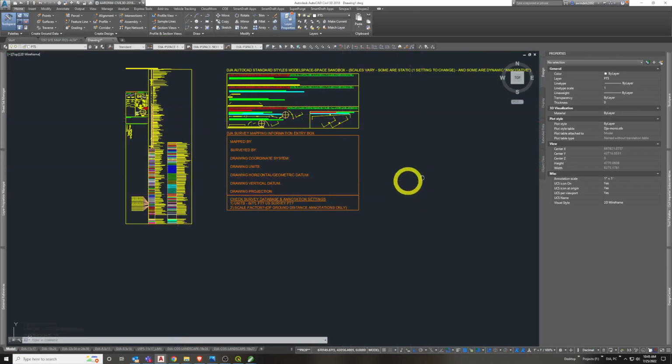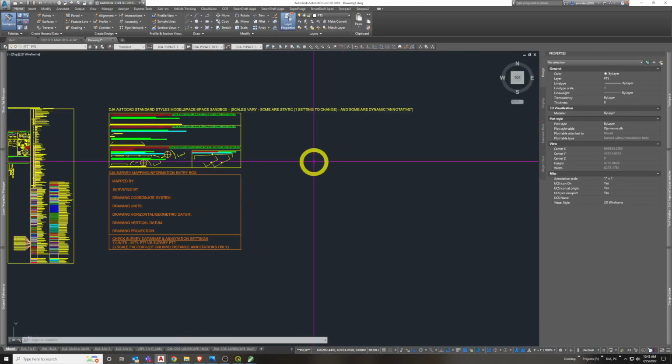And this is very relevant currently. We've seen a lot of errors when coordinate systems are set up: the map insert command likes to scale to seemingly random amounts, which has been a problem lately. But oftentimes when you start with a blank template or a full blank AutoCAD file, this issue is eliminated. The way it populates seems to be when you set a coordinate system.